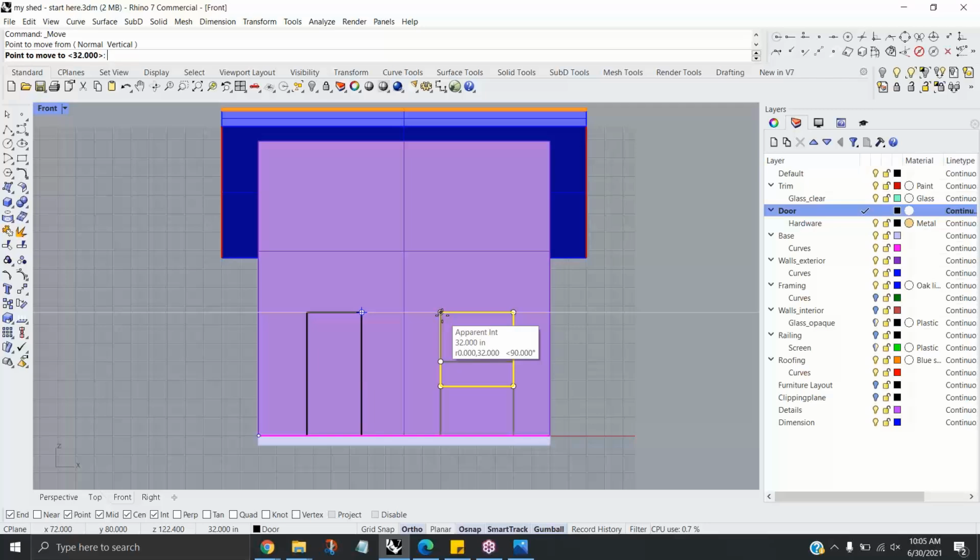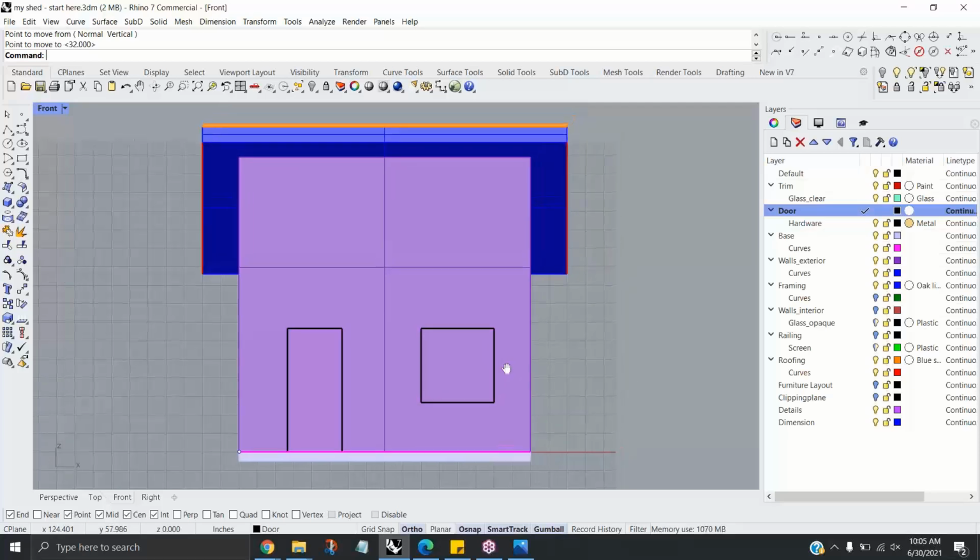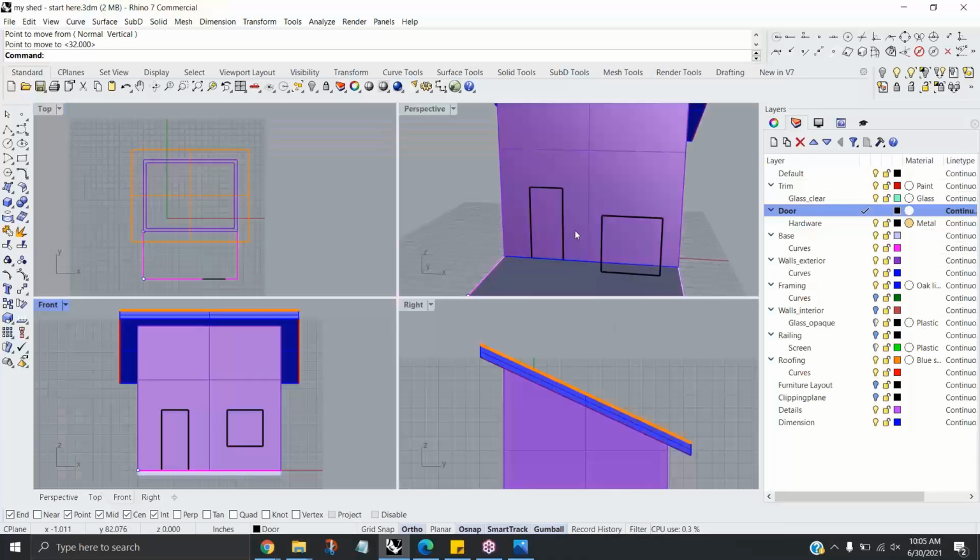And that's the problem that I see with starting to use Smart Track, is that it's not a pick, it's acquiring. You put your cursor over and move it away. That will take a little bit of practice. So if you don't have time to practice, just draw a line. It's perfectly good, and then delete it. It's just some construction geometry that will be really helpful, keep things accurate, and then keep you moving forward.